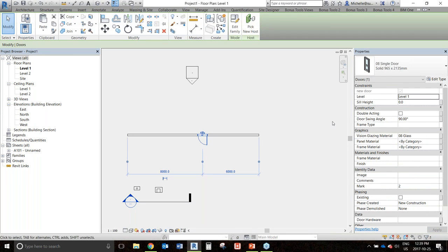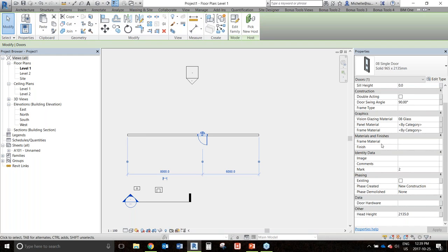So the organization can be really important to the end user to make sure that they know where to find things. The same can be said when you're starting to add data to your project for the door schedule and such. You want to come up with a plan for where you want all that data to be. The only thing that makes this kind of difficult is when Revit puts in out-of-the-box parameters that could also be used for your door schedule, things like frame material and finish. You have to make a decision whether you want to use those or whether you want to just tell your staff, everything that we're scheduling is going to be under door data. But I would really try to use the out-of-the-box ones, and then just point your staff in the direction, and that kind of comes with standards.